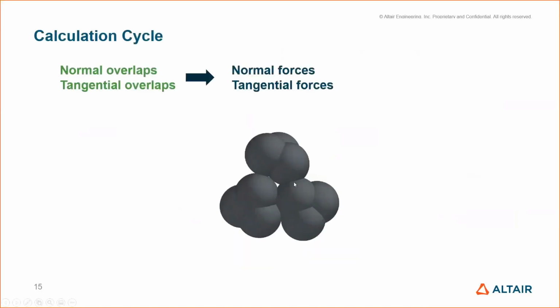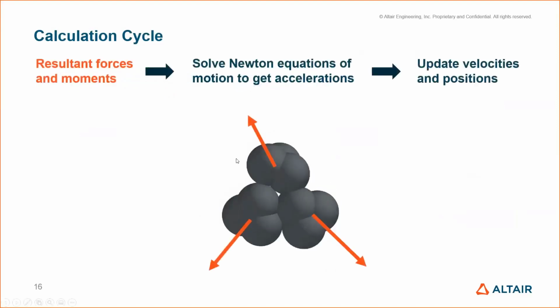And it's when the particles collide we get the overlap. The normal and tangential forces are calculated on the particles from this overlap. And this calculation happens every time step. From the overlap, we get the resultant forces and the moments, and using Newton's laws, we obtain the accelerations, and through the numerical integration, we update the particle positions.